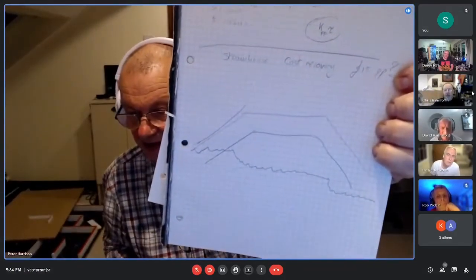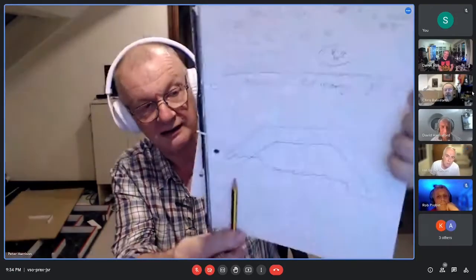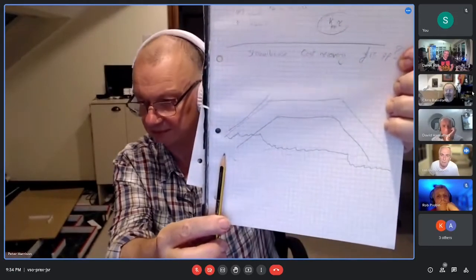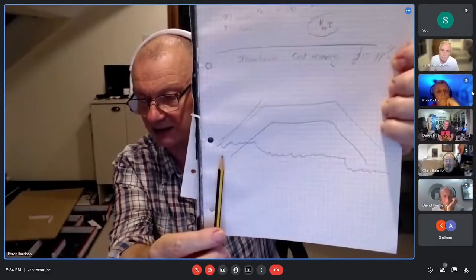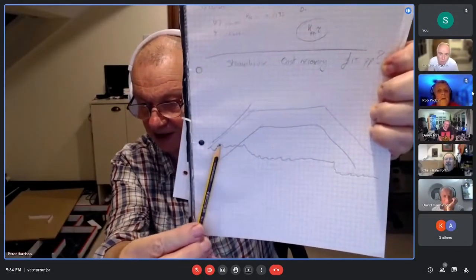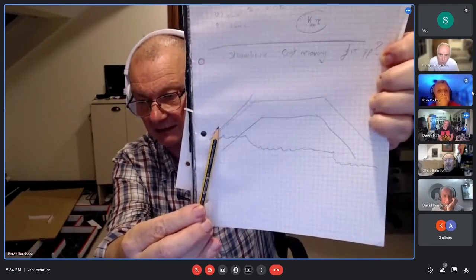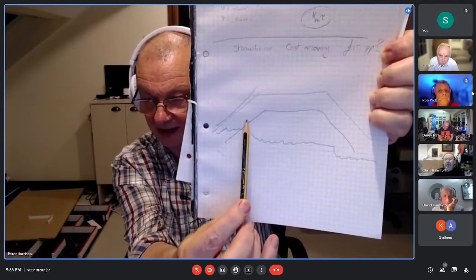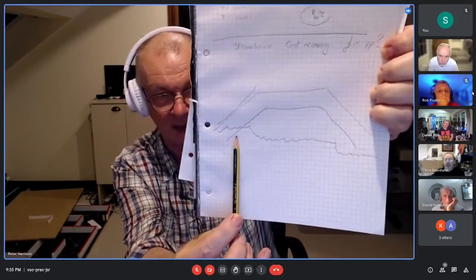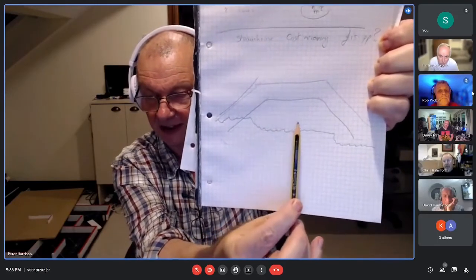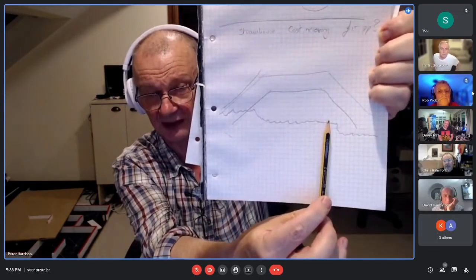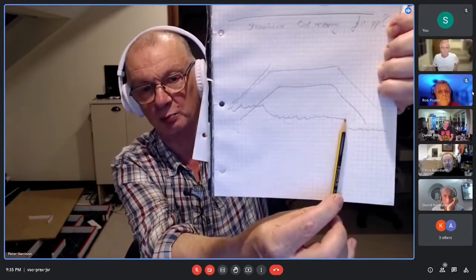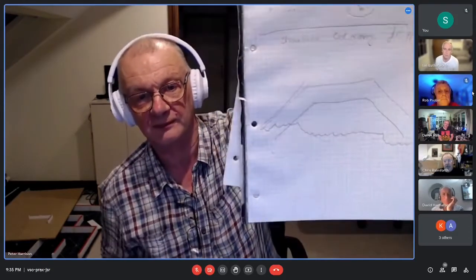Is that the start on your screen? Yeah, right. So at the start, the controller will try to compensate for the lack of acceleration by providing a step. And then once it doesn't have to accelerate, that step will go away and you'll get zero output because the feed forward is sorting things out. And then when it tries to brake, the controller will provide that braking torque. So it'll all still work, right? But now the controller is filling in the acceleration portion.